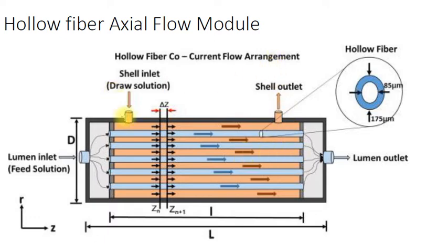If it is reverse osmosis, permeate will just permeate out through the membrane. These tubes are made from the membrane. So permeate just flows in this direction, is collected in this shell chamber, and is removed from this side. This type of hollow fiber axial membrane is generally used in ultrafiltration setups, and it is quite useful because the membrane densities are quite high, but this type of setup only uses hollow fiber membranes.